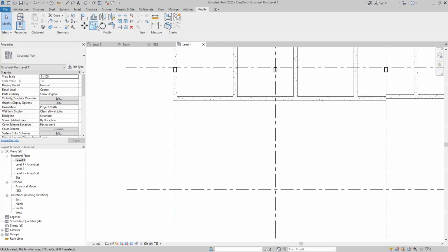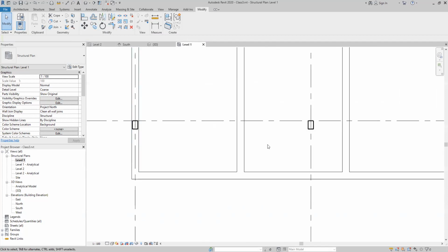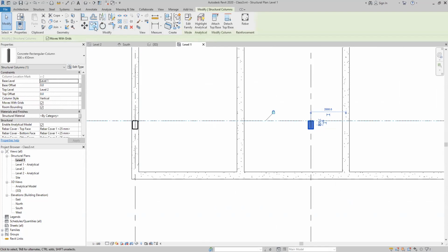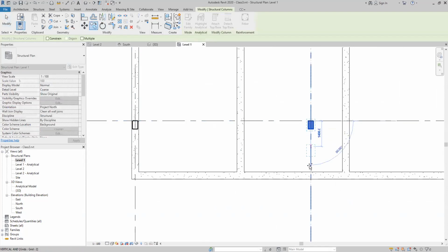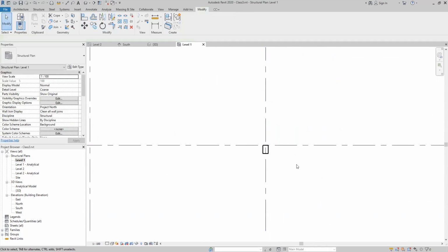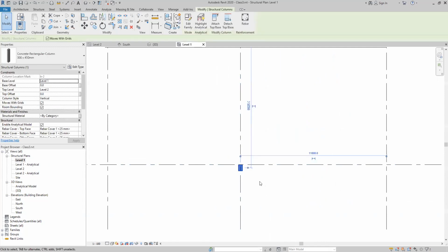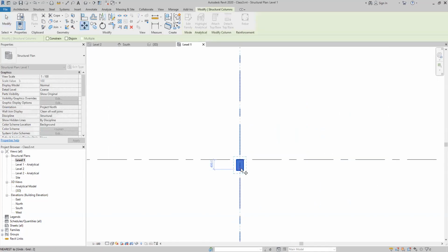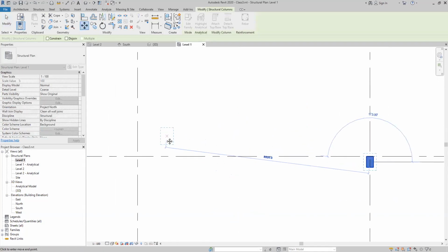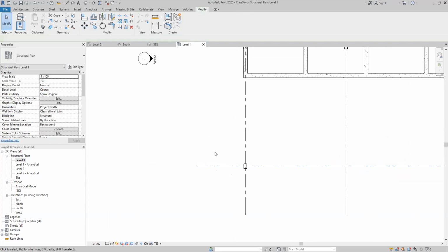So quickly we go, copy and move are almost the same, right? So it's a very fast one. So I quickly do it. Copy is the easy one. What you want to do is select the elements, select copy, and pick the point and move to the point. Okay, easy. Right. I don't need to spend a lot of time. Similarly move, select the element, click the move option, pick the base point, then move to the place point. Okay, you can move from here to here, right? So these two are very easy, right?